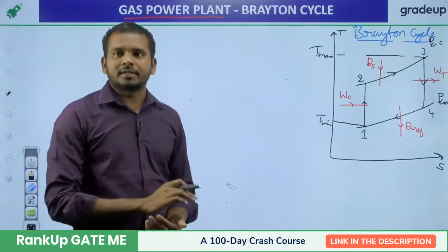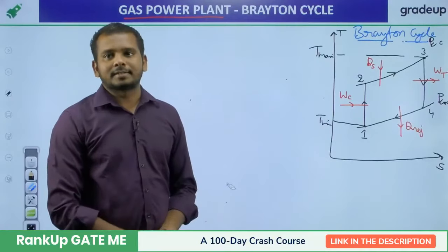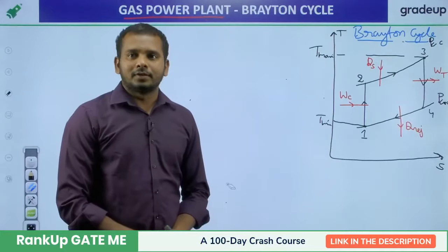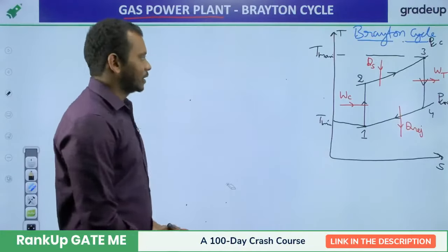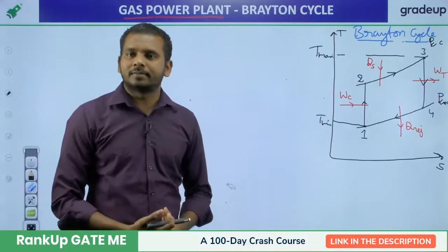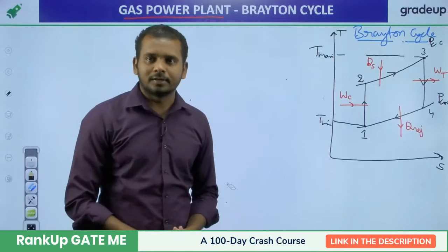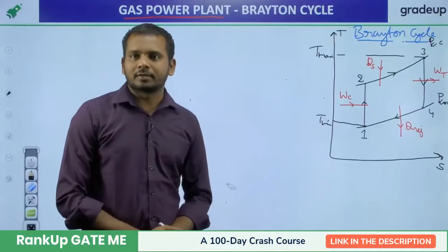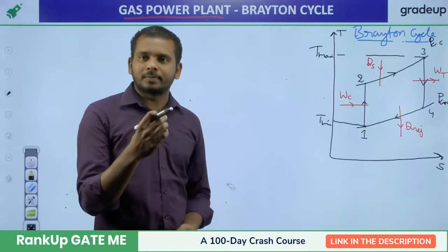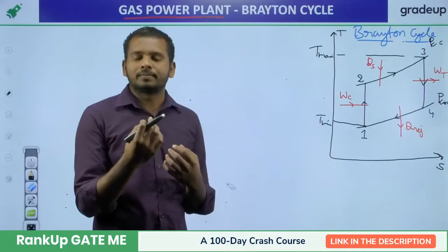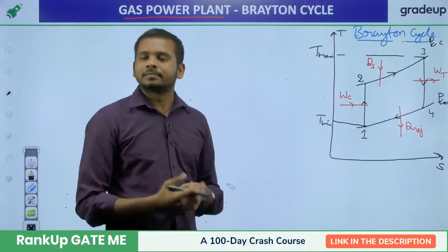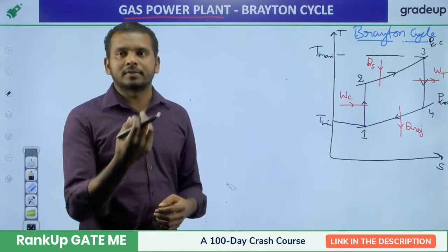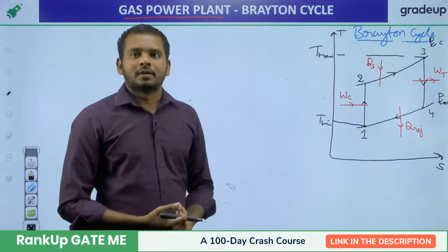Sir, is it necessary to take the compressor work, as it is run by the turbine and the compressor work is small? Hi Chandan Sharma. You're right that partial work from the turbine is used to run the compressor, but at the same time the compressor work is not small. It takes significant work. In case of a pump, it generally requires less work compared to the compressor, so we can neglect the pump work. But in case of the compressor, we cannot neglect the compressor work because the compressor requires significant work. Right?